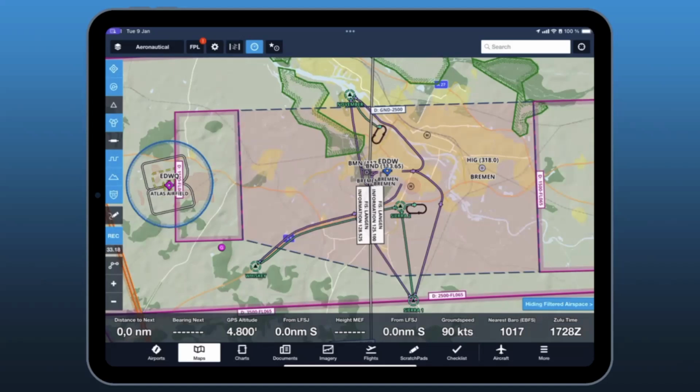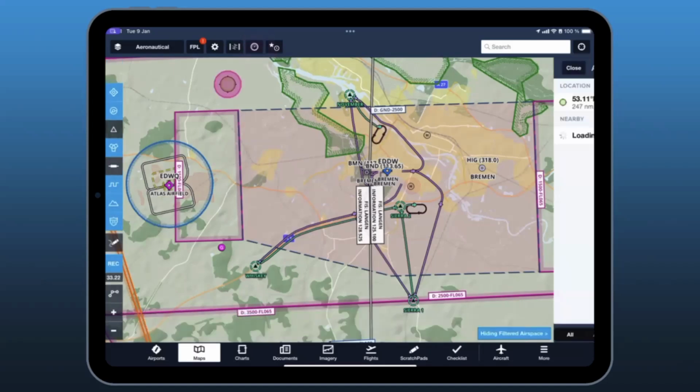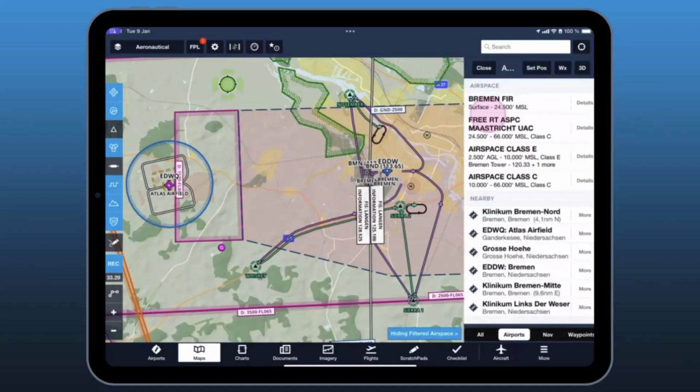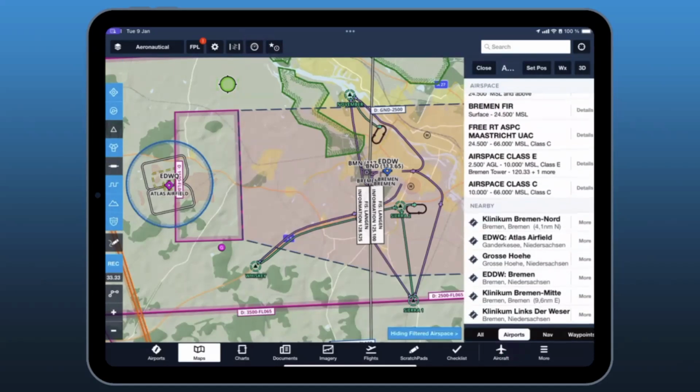That is permanently updated during the flight so that you always have the information what the nearest airport is. The other option, when you don't have that instrument line, is to tap and hold the map and you can show airports in increasing distance from your current position. That includes all airfields, including helicopter landing fields, glider fields, and so on.